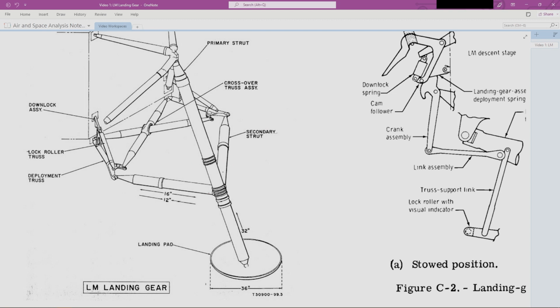Okay, so I touched briefly on the secondary struts, but essentially, you have a point up here, and imagine the primary strut as a pendulum that can swing in any direction around this point. What arrests that swinging is the secondary struts, right? Imagine a pendulum that comes down and can swing in any direction it wants. It can swing in a circle, or back and forth, left and right. So you need to constrain that swinging motion. That's why you have two struts.